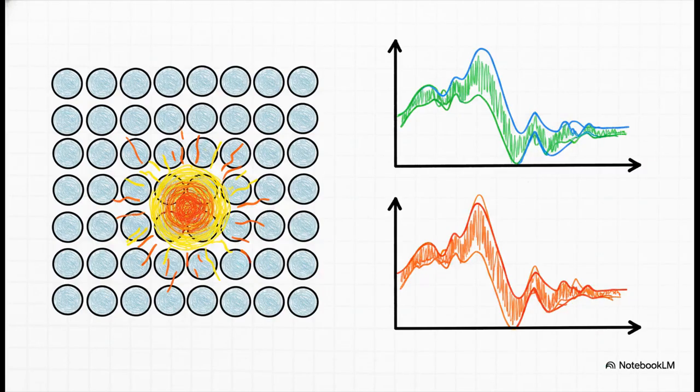And the main reason they obsess over all this math? It's all about the power peaking factor. Because even if your reactor looks completely safe on average, the power inside isn't totally uniform. You get hotspots. And the crazy thing is, the single hottest fuel pin in the entire building dictates the safety limit for the whole operation. If that power peaking factor gets too high, that one specific pin could melt. So flattening out that power distribution isn't just about efficiency. It's a critical safety requirement to make sure our tightrope walker isn't leaning way too far to one side.